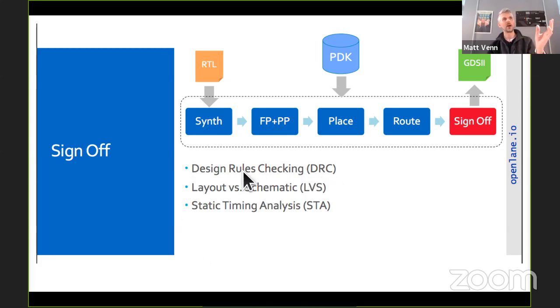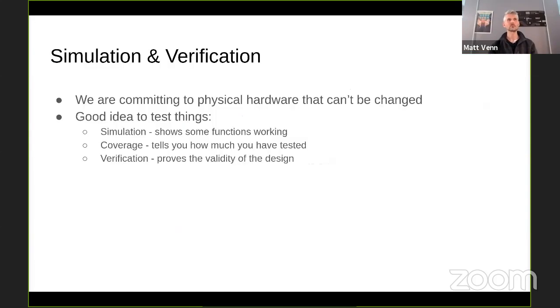So if OpenLane finishes without an error, it's DRC clean and it's ready to send to the foundry. Although one thing we've not looked at yet is the pad ring, and that's the bit that the design fits into that has the bond pads that break out to the chip. So that's what we'll look at with the Google Shuttle. Which is the next but one thing.